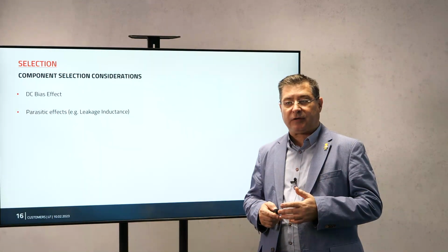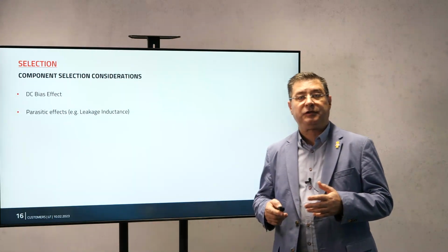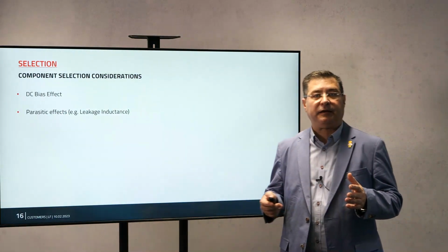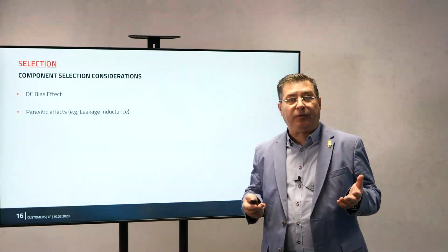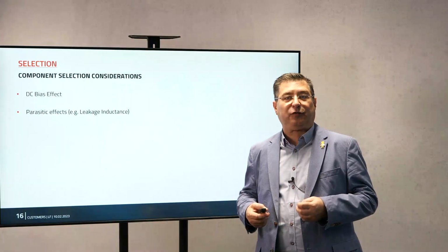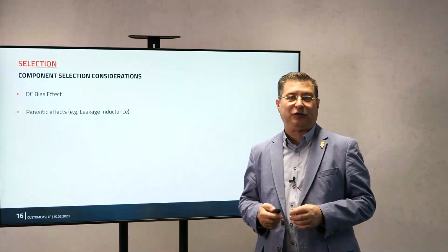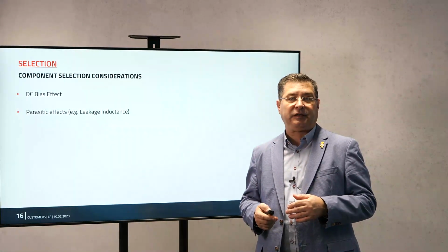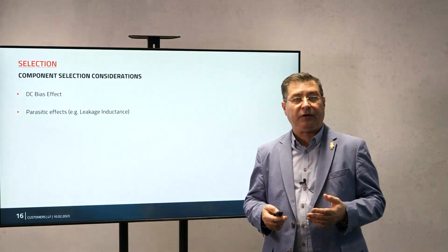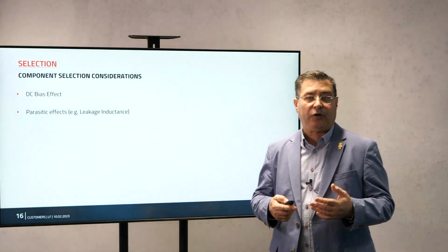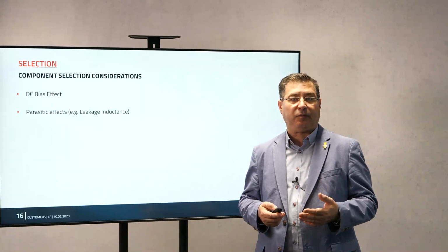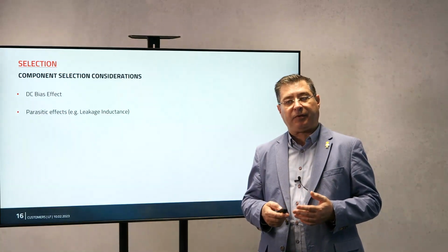The next point is, again, the parasitics. Don't simulate ideal inductors and capacitors. We cannot build them. You get free of charge all the parasitics. We don't charge you for them. But please consider the parasitics, because they will occur even if you are using models of ideal components. Please use a library with the parasitics.